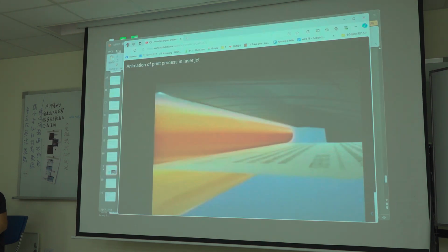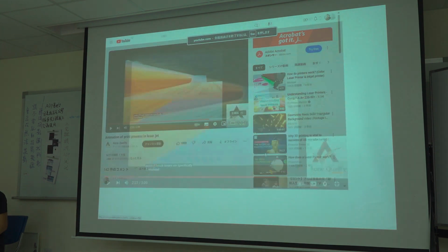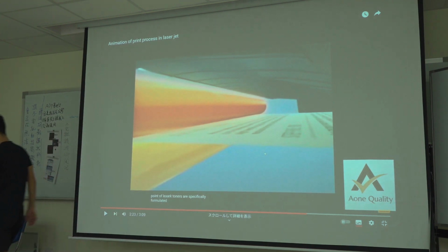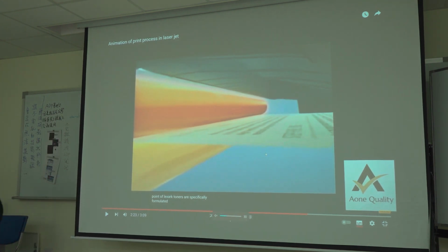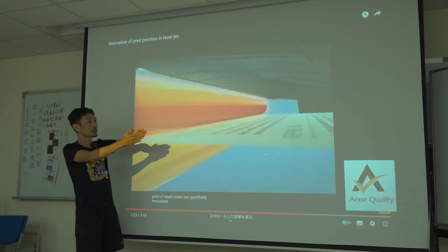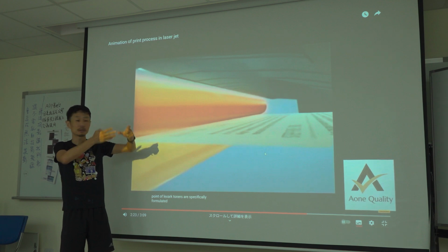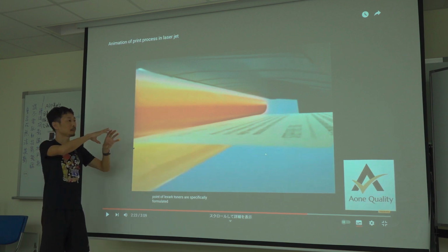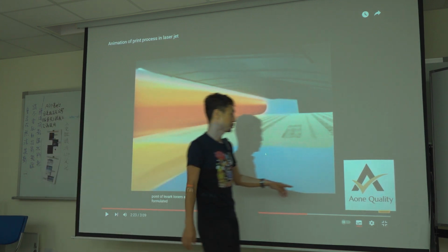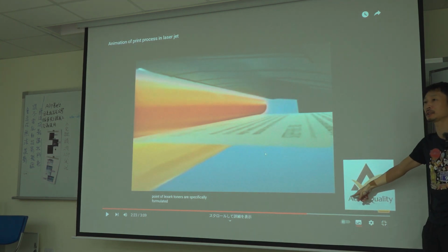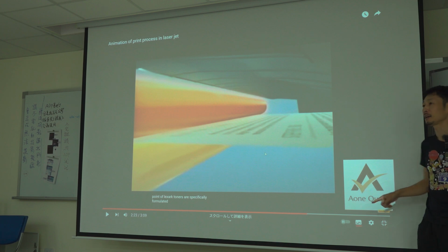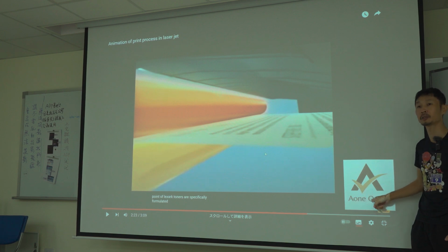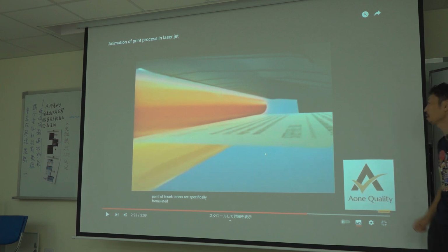Okay, so just like we're talking about that, if I understand correctly, I should mute this, right? Using this very sharp edge where the electric field is very strong, they carve the letters onto the drum. The part where you want to print, say you want to print these letters, is I think positively charged, and the toner is negatively charged. So when toner comes in, only these charged parts get printed. That's how the laser printer works.